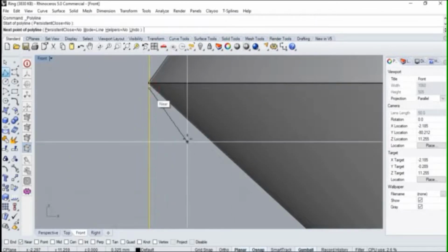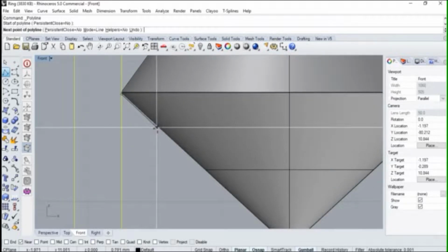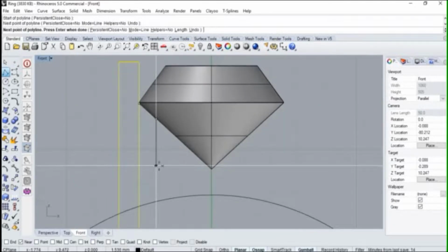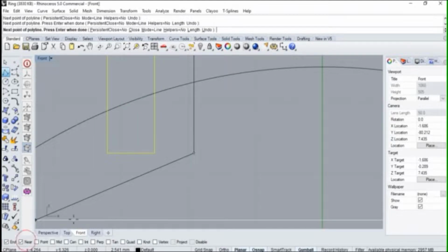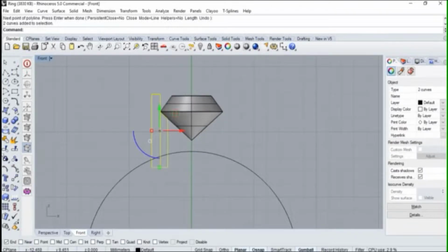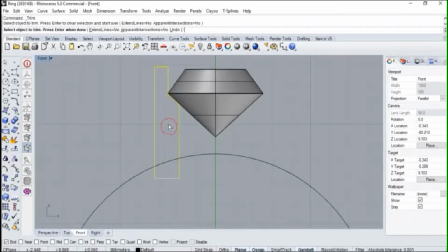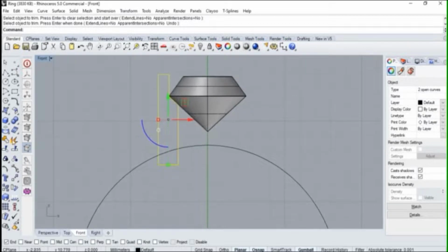After that I will take a polyline tool and just create a kind of angled line like this and complete it using end snap. After that I can just trim it out and remove this center part. And one thing, when you're creating this angled line, just make sure it is more than 0.5 from this line to this line, this point, right? It should be more than 0.5.